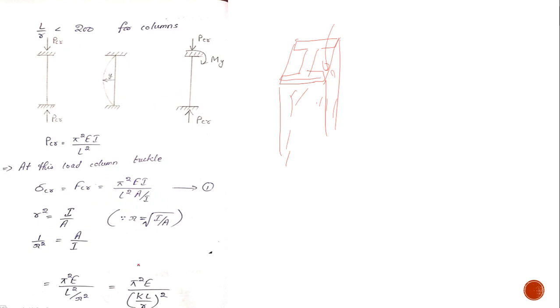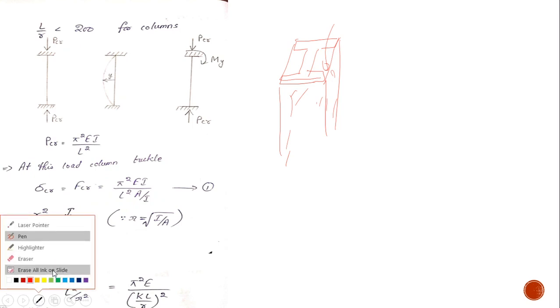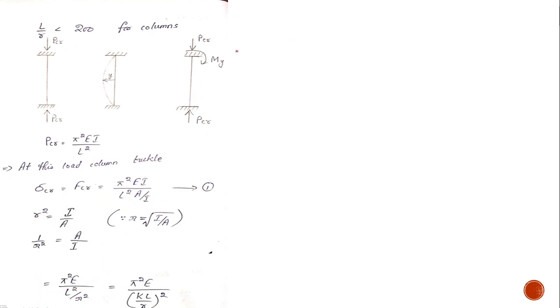For the first time, you have to design a column on its yielding limit state. Limit state means that it's on its failure state. So for the first time, a scientist whose name was Leonard Euler gave his equation about columns. He used simple mathematics, and he asserted that a column may buckle or fail under critical loading.